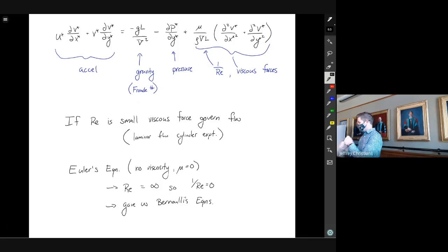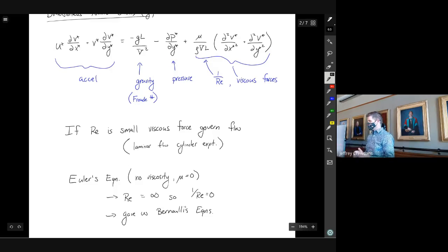And we could do that because the Reynolds number was essentially infinity. It was really big. So we knew that the viscosity term didn't matter and we could just look at pressure. So looking at fundamental physics, when we try to boil it down into non-dimensional groups, it's a way, without having to do any of the hard work of doing significant calculations, you can figure out what are the key forces and what are the key factors that are influencing this system.